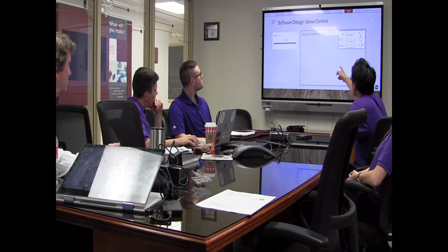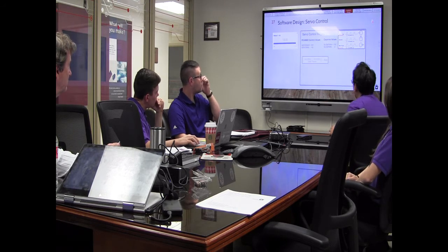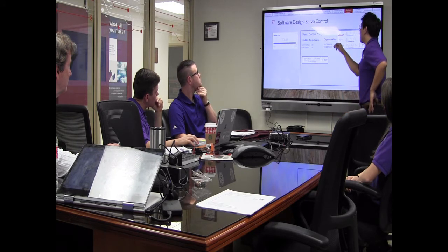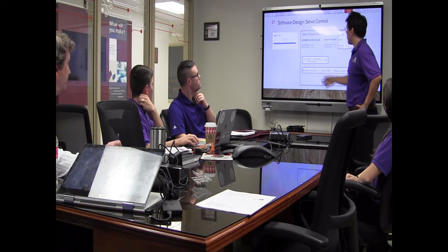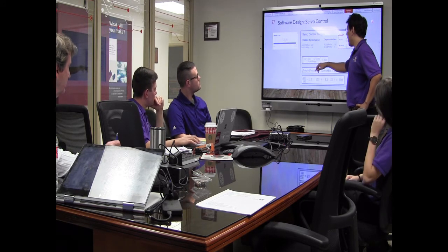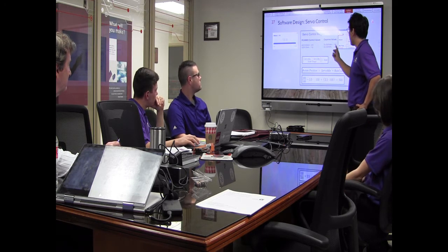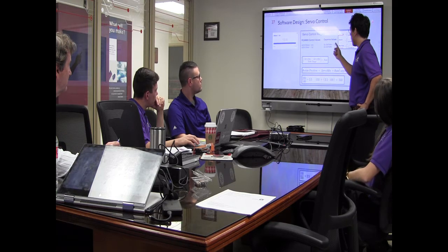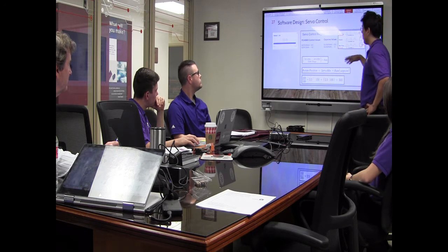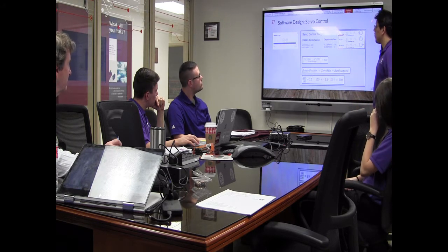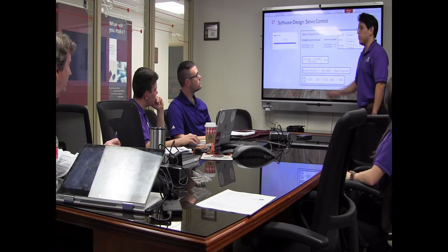So right now we're going to servo control. If you just keep pressing, this is how we're controlling it. Just wanted to give you an example. Here's the slider min and max from 0 to 100. Here are its ranges, and we do a little math, getting the range and finding a multiplier that multiplies with the 0 to 100, and then finally we get the specific rotate position for our window blinds. That's a nice way to show the math-related function that's being used.